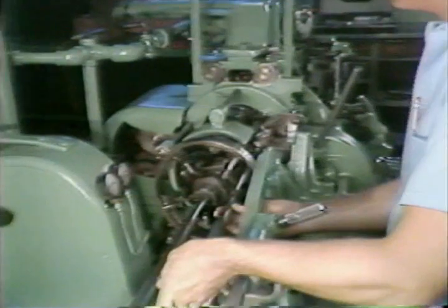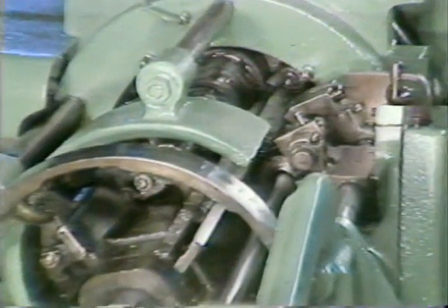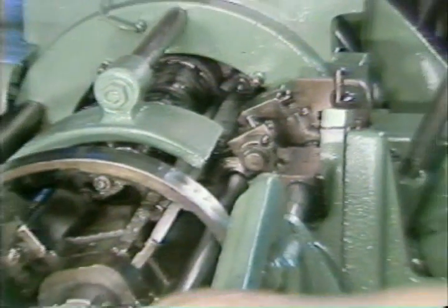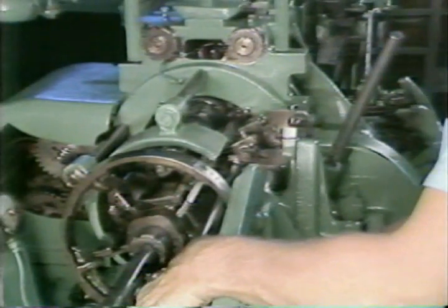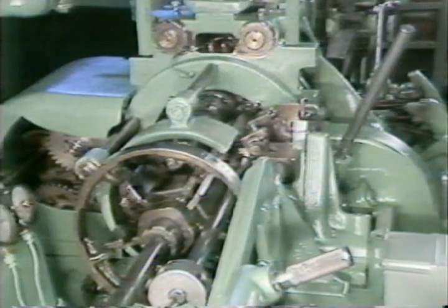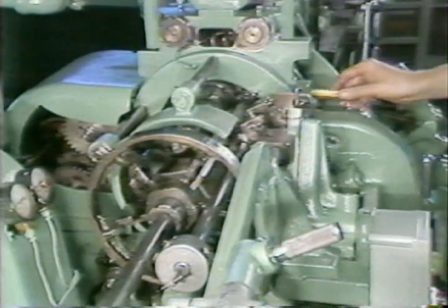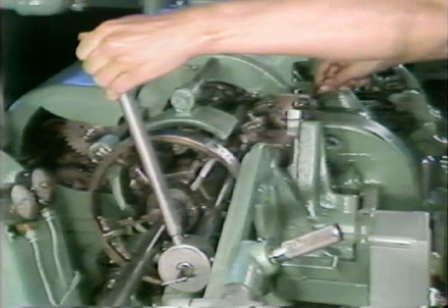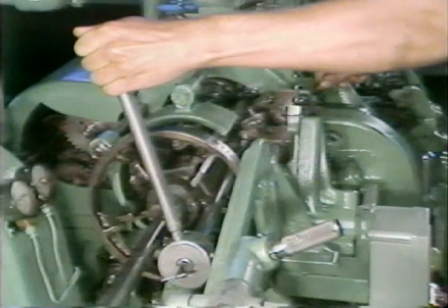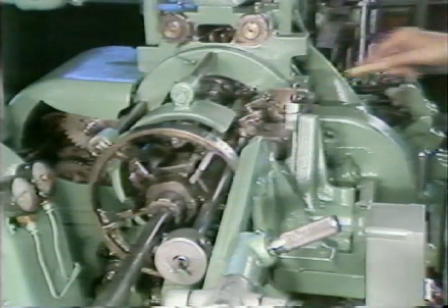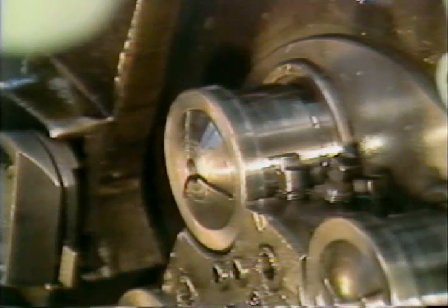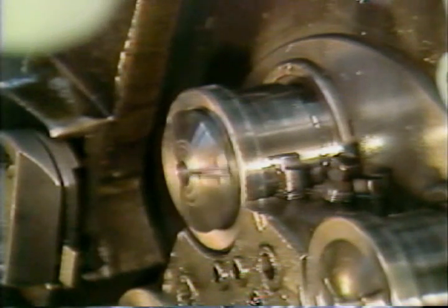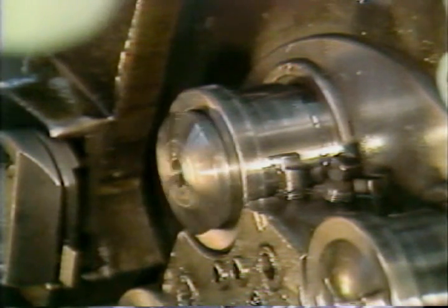Once the pusher is removed, the collet wrench can be inserted into the back of the spindle. Rotate the collet wrench until you feel the pins engage the collet. The brass bar can now be placed into the spindle gears. The handle can now be inserted into the collet wrench to break loose the collet. Turn the wrench in the right-hand direction. The collet can now be unscrewed and removed.